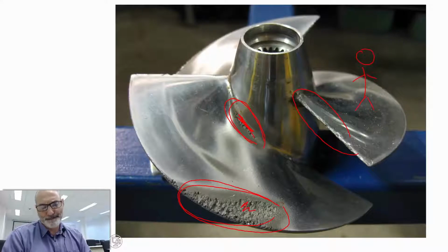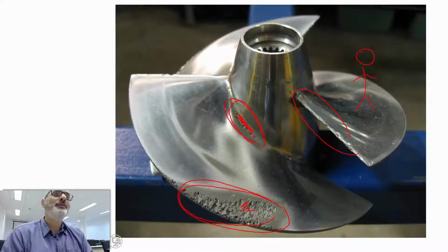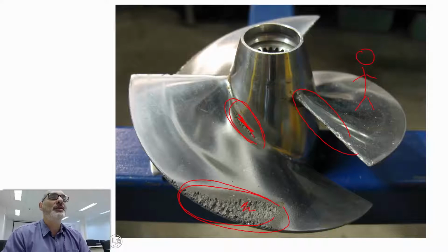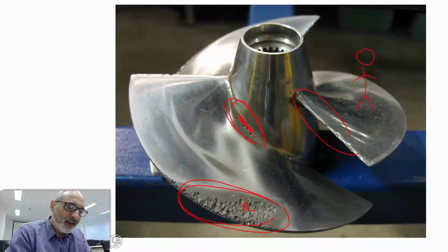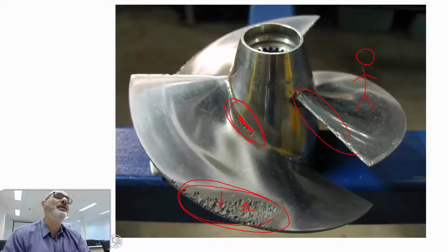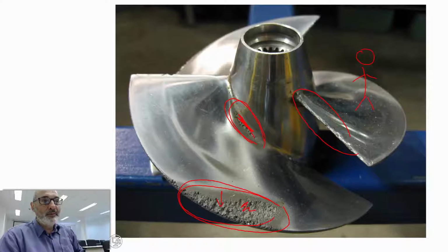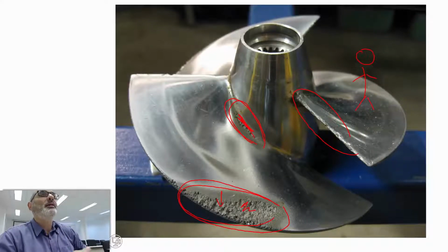Is there a problem in water pumps also, no? Yeah, cavitation, exactly. You may have this, it's the same thing. Cavitation related to these very huge pressure variations due to the implosion of these cavitation bubbles. So if you could see with a microscope, it's like having microscopic hammers impacting on the surface of the metal, and you have this kind of erosion. It's a very big problem even for ships. You have this in ships also. Cavitation is a very significant problem.